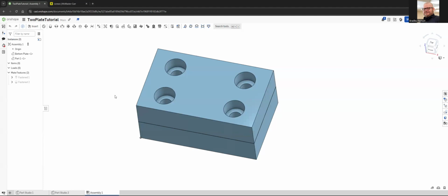Most CAD programs can handle imports. Now, I may not be able to import SolidWorks native files, which is fine, because things like IGES and STEP files are designed for universal import. So if it won't import the SolidWorks, I'm fairly confident I can figure out how to import a STEP file, which McMaster also provides.